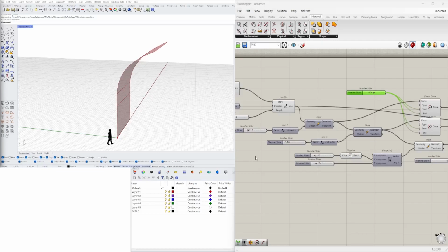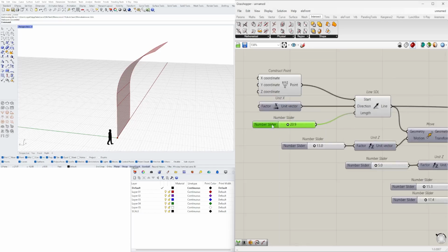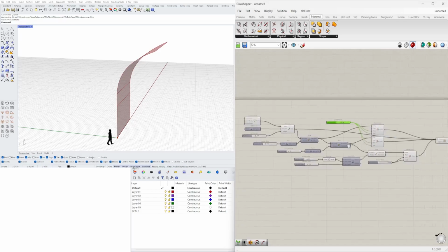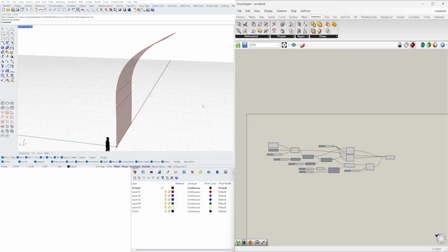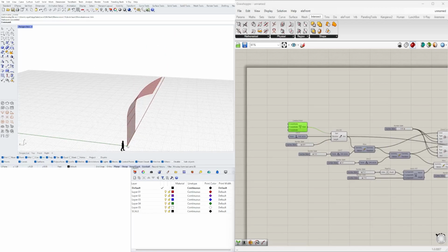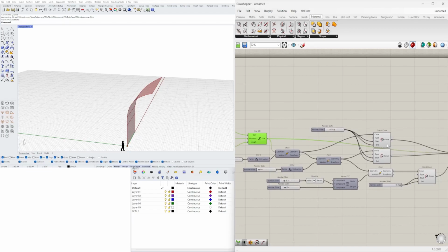So at this stage, we can organize this because we know what each and every component in the slider does here. The thing we need to also be aware of is now we're going to be doing this again, but moving it over to the left, but making sure that we don't do that with the top curve. So we'll be moving in the negative Y direction, all of these line segments.